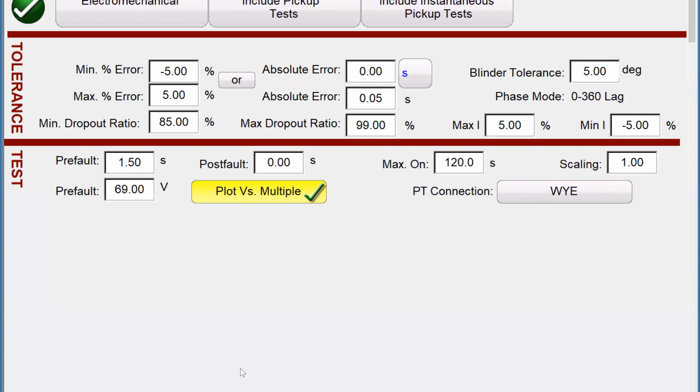Okay. All right. So since it's hard to run multiple things at one time, I think what's killing me is my communication between my PC and the relay is not talking. It's not making good connectivity there. I am driving the test set, just so everybody knows. I'm injecting the current amounts like we talked about earlier on how we were doing the inverse curve.